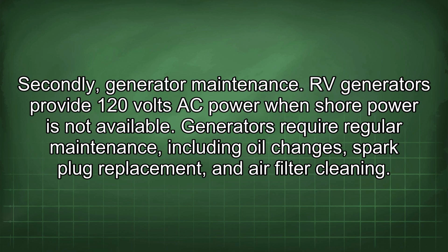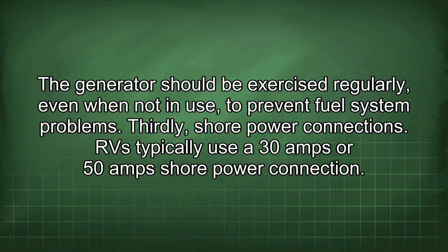Secondly, generator maintenance. RV generators provide 120 volts AC power when shore power is not available. Generators require regular maintenance, including oil changes, spark plug replacement, and air filter cleaning. The generator should be exercised regularly, even when not in use, to prevent fuel system problems.